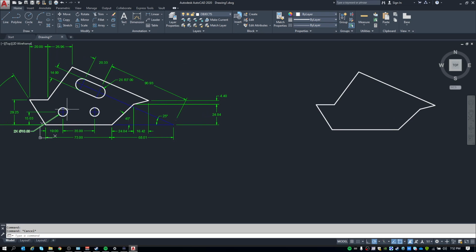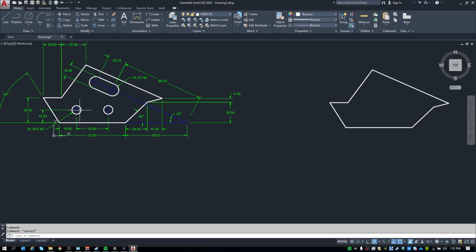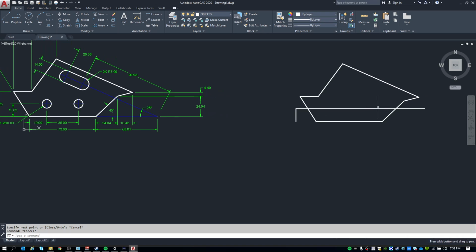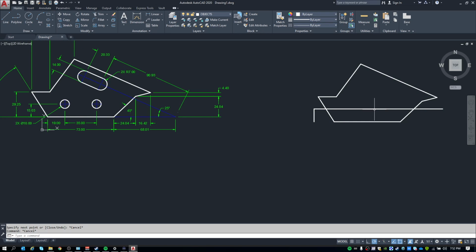So next we're going to do these circles. It's pretty simple. Both of these circles have a vertical height of 15.03. So I'm going to go ahead and draw a line up at 15.03. You just go straight across. And we know that this is the line that those center points are going to be located on horizontally, or x-axis wise. I'm sorry, y-axis.